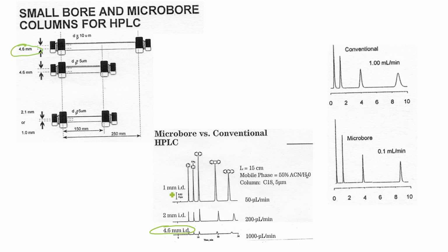But if I go to a smaller ID, down to these 1 mm IDs, so now I'm what's called a narrow bore or micro bore, my flow rates have slowed down substantially, and what I see is those peaks got a lot taller, right? So now they're easier to detect. So smaller IDs, better. So smaller column ID, certainly better.